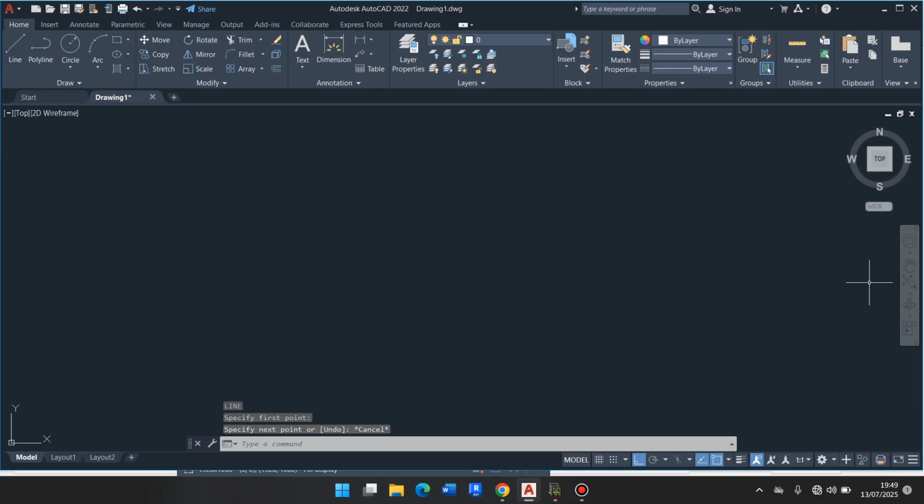Now the last thing to do just before I begin to draw is to set my layers. Okay, now some people can ask, why do I have to set my layers? Well, you need to understand how to use your layers even from this onset, because by the time we proceed and we get to designing with Orion, you're gonna see how different layers work when you import your drawing from Orion to AutoCAD and you need to clean it up. You're gonna do it by using layers.